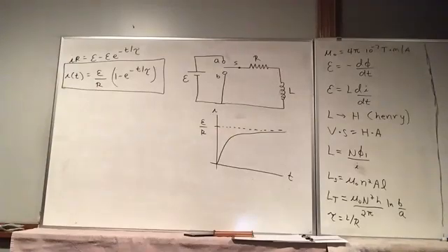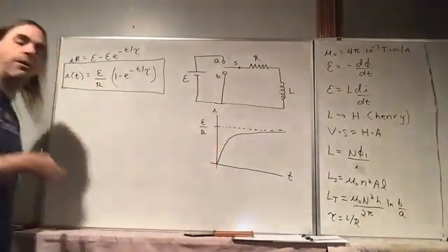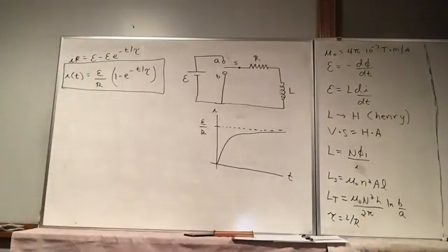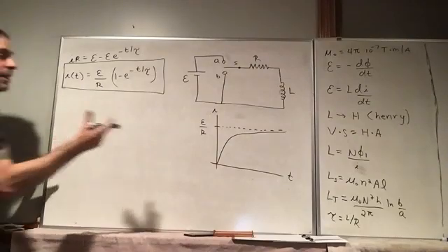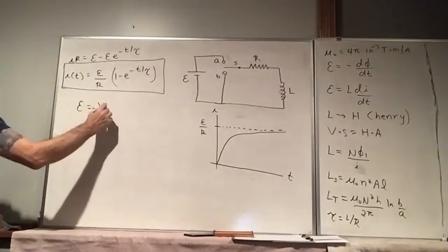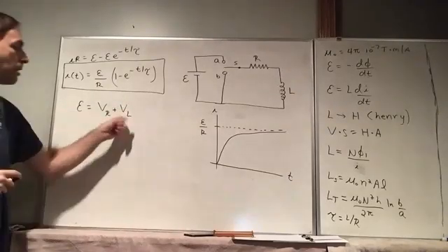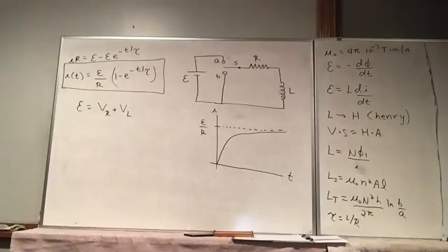We can see di dt is the slope. So it starts out with a large slope. Here, di dt is a very steep slope. And so there's a large voltage drop across the inductor and a much smaller voltage drop across the resistor initially. In general, we can say that the EMF provided by the battery has to equal the voltage drop across the resistor plus the voltage across the inductor.